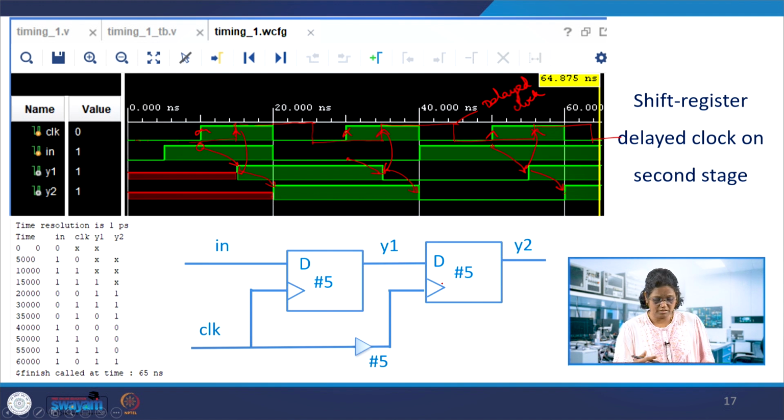So this is what happens when you have delay in sequential assignments and sequential execution with blocking assignments. The first delay forms the second delay also, and you can notice the important point: the second delay means y1 is sampled at the delayed clock of the two registers.